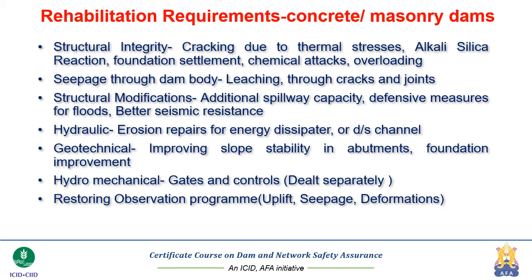And for chemical attacks, we may have to remove the spalled concrete, the deteriorated concrete, and then provide new concrete with polymer additives or with additives which are capable of resisting the corrosion and attacks. There can be high performance concrete requirements in case of erosions.